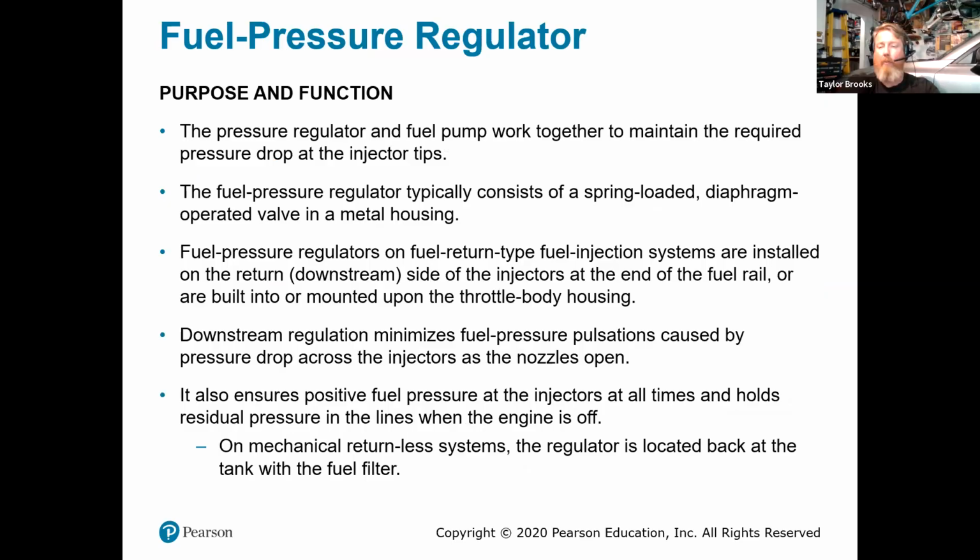Now, we brought up regulating the fuel, and regulating the fuel is going to be important because we're going to have the fuel volume need to increase with throttle load. So we're going to try to maintain the pressure while we're operating the engine. How we're able to do that, but then also increase as pressure decreases in the intake manifold, or less vacuum, is through a pressure regulator.